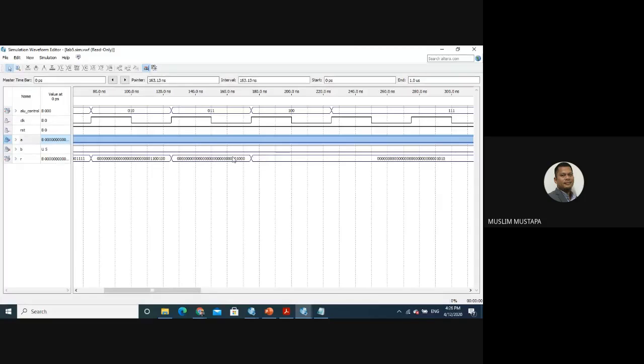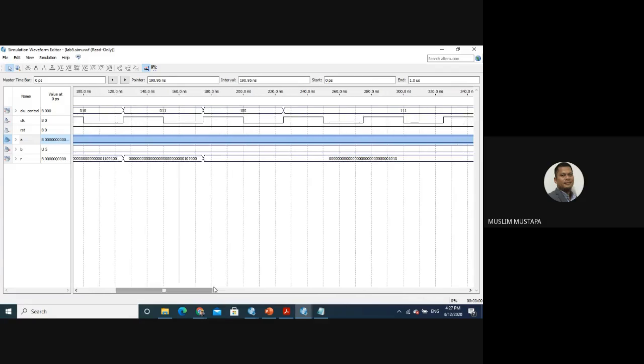For shift left, we are moving everything to the left, so the LSB will be replaced by 0. We are shifting everything to the left and adding 0 to replace the last bit. For shift right, we are moving everything to the right, so what is on the right gets kicked out, you see it no more. Then the one that replaces the MSB is also 0. So left and right shifts will be replaced by 0. That's what the code is doing.